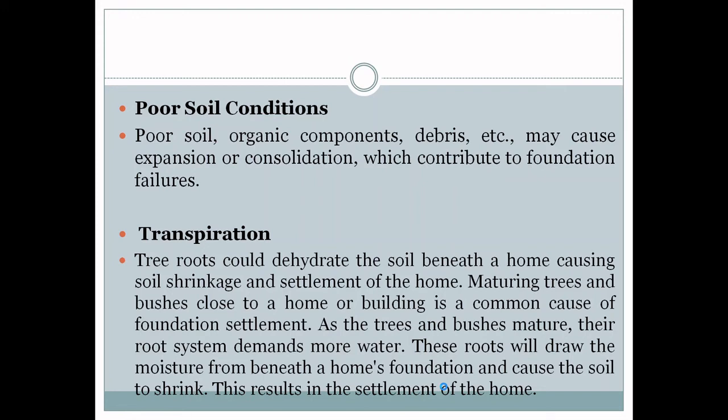As the trees and bushes mature, their root systems demand more water, and these roots will draw the moisture from beneath the home foundation and cause the soil to shrink. This results in the settlement of the foundation or the home.